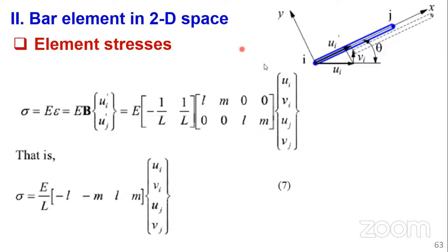So basically what we're talking about is the stress in this member. Stress is equal to force over area. For the stress in this member, we just need the quantity that contributes to a stretch, whether negative or positive. Of course, negative stretch is compression, depending on the type of axial load applied, whether compression or tension. So we need to disregard the quantities Vi and Vj in the local coordinate system.